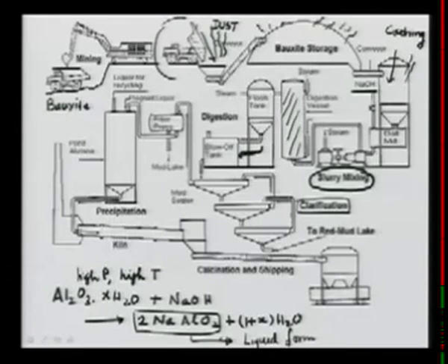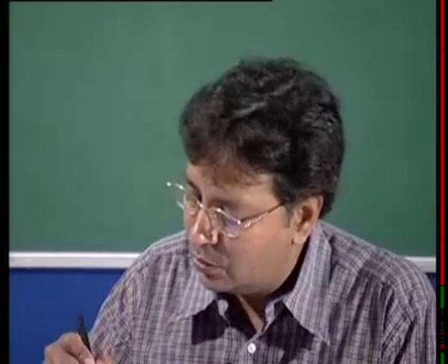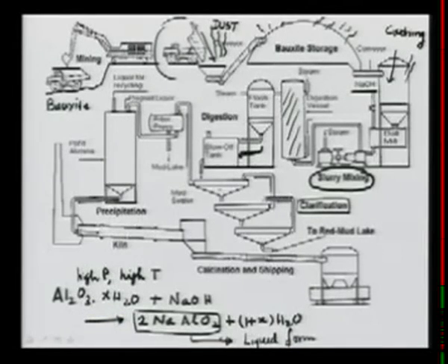Essentially what we are trying to do is separate out the suspended solid components, which are the impurities. So what you see is settling tank number 1, and then it becomes concentrated here, the sludge, then it goes in here. This is the first one, the second one, and the third one.